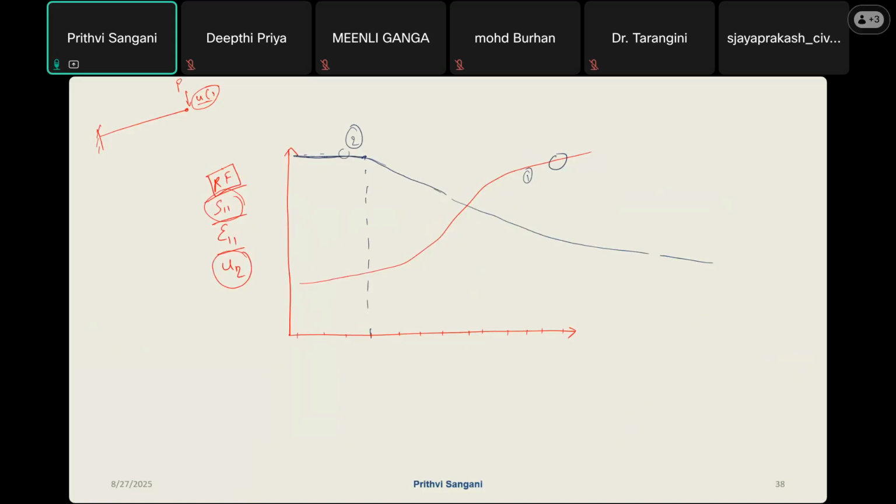That means even if I go for a very small mesh, I'm going to get the same or similar results. So why should I spend a lot of computational time going for a smaller mesh to get the same kind of results which I get at this point? And if I go for a larger mesh size, my results are always varying, all the time. That means these are not constant, and they are inaccurate.